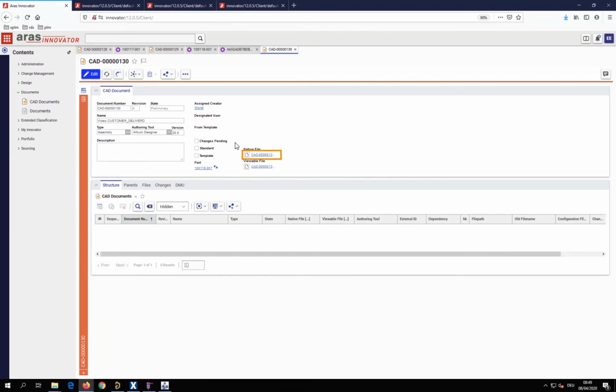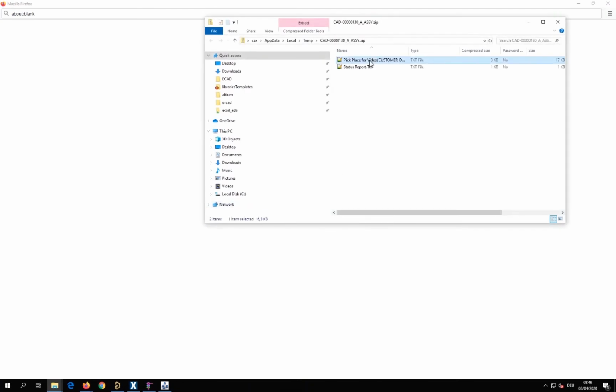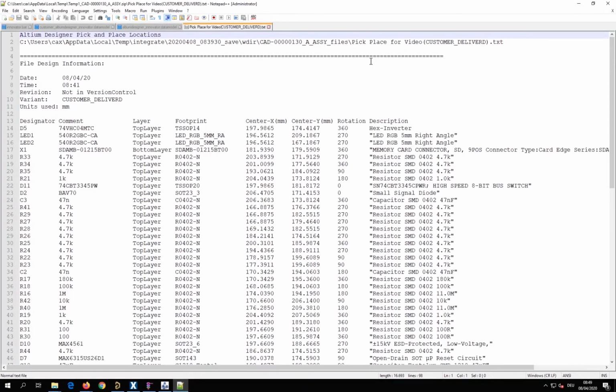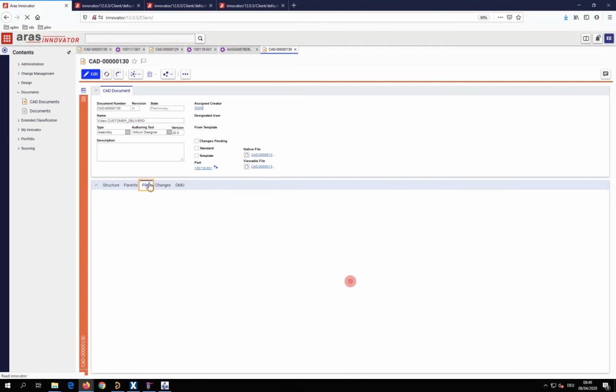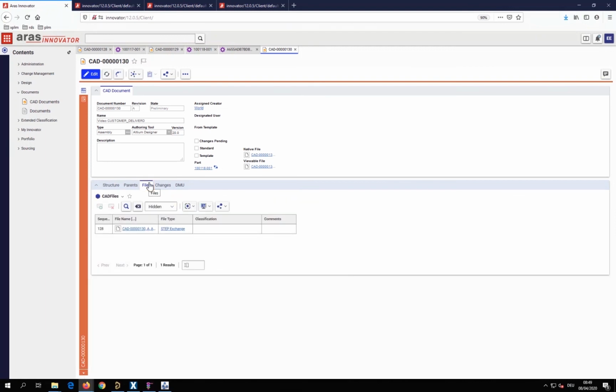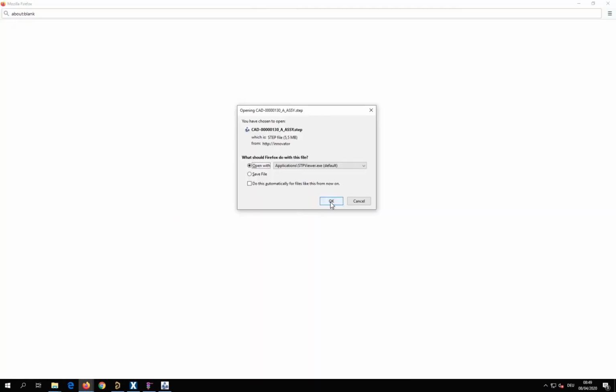For the assembly line, we need coordinate data. This file is usually known as the pick and place file, and additionally includes rotation and other instructions for the placement machine. Finally, this viewer shows the step model of one of the design variants.